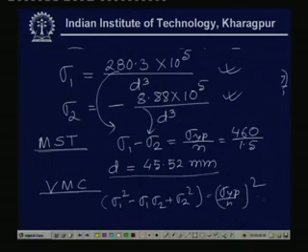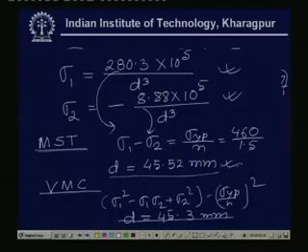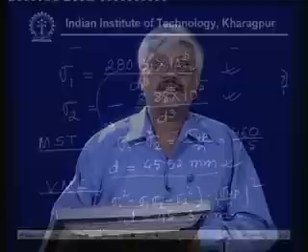If you put these values accordingly, it will give something like 45.3 mm. You can see that the maximum shear stress theory is coming out to be the most conservative one compared to this one. So, this ends our idea of how we calculate the diameter or the machine member dimensions based on fatigue. Thank you.